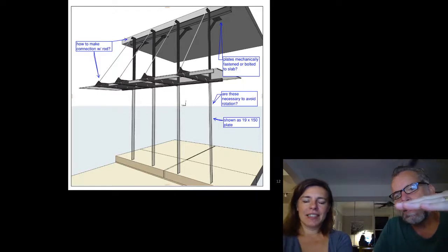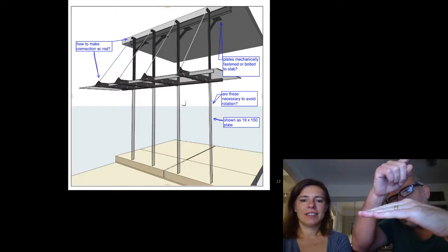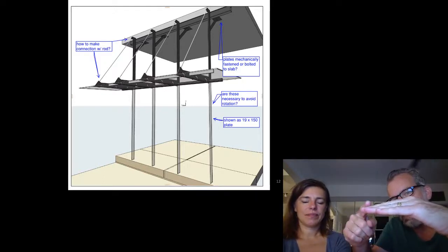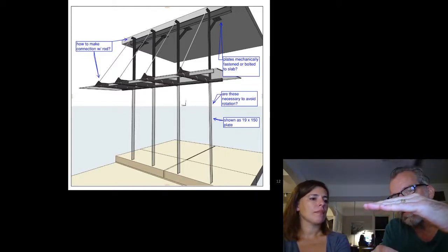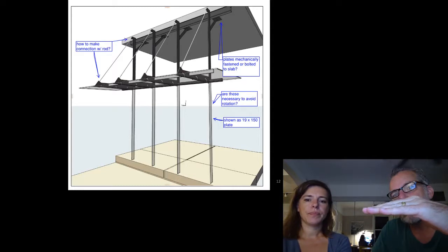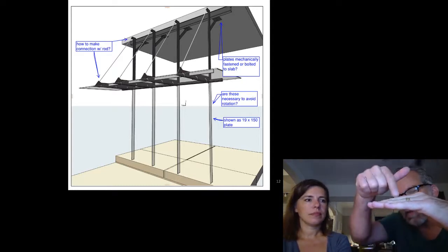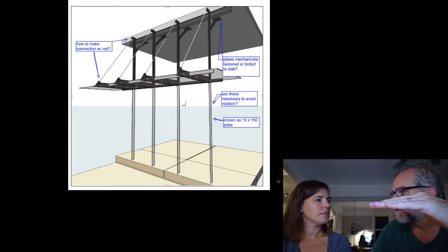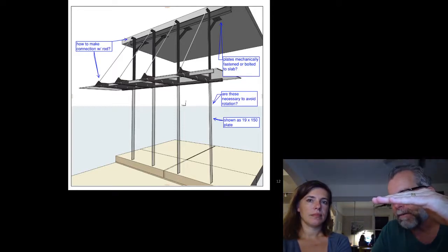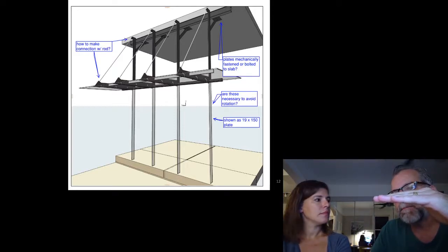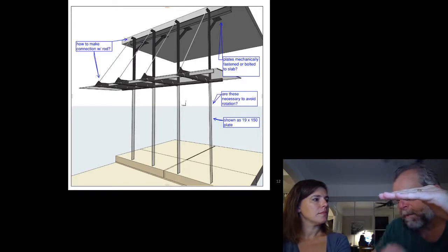One is the condition where we have a hanger rod and an uplift rod. It's uncommon, but it's something that we can do, have a 2-rod system. And then the other one is ballast. Ballast is extremely effective. We have uplift in the order of 1 kPa, just crudely. Patio stones weigh about 1 kPa.